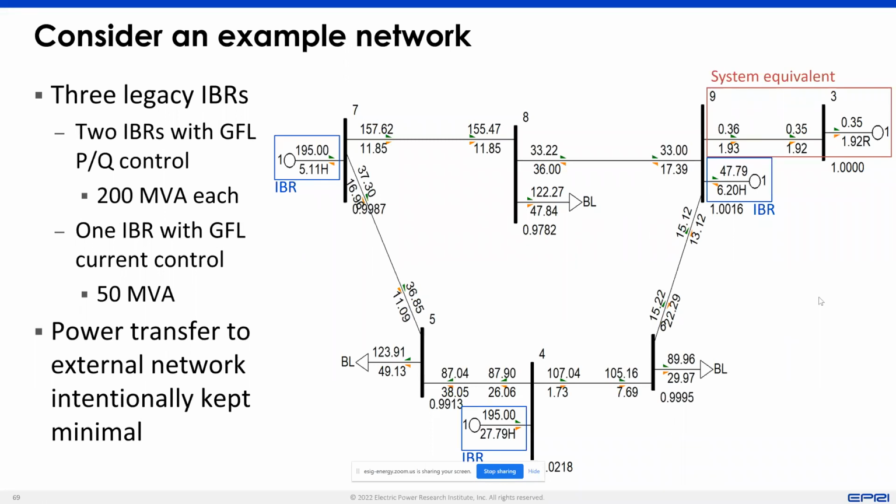This also leads towards one of the points we previously had, that it depends upon the location and the sequence in which you're installing these grid forming inverters. So take this example where you have an existing system. Say you have 3 inverters which all have grid following characteristics for now, and you isolate this system. The goal is to create a small signal disturbance, because we don't want to look at the large signal perspective for now. Supposing you create a small signal situation where you isolate the system equivalent, then the amount of flow to the system equivalent is very nominal, right?